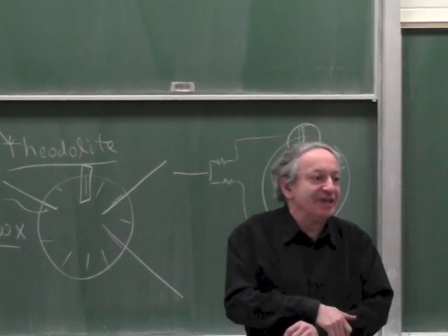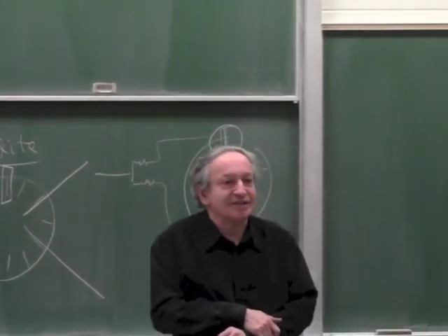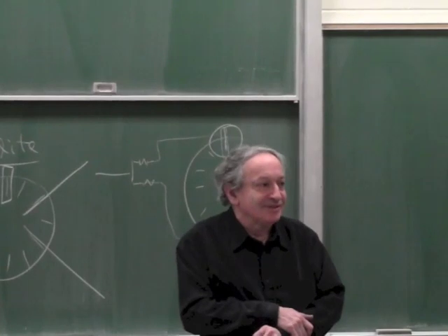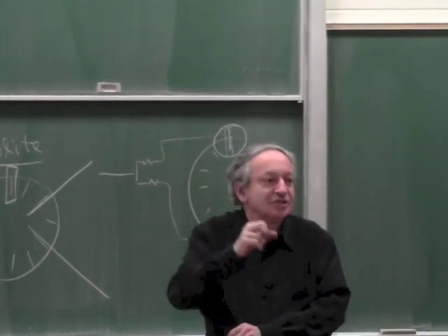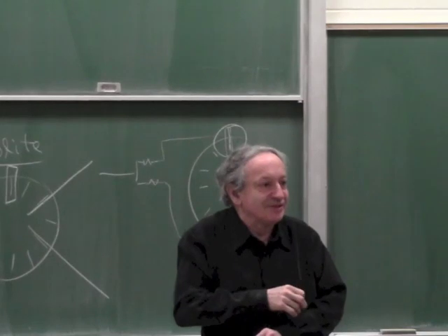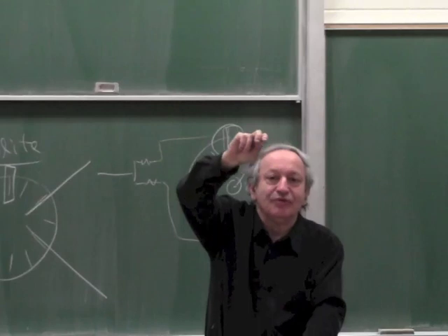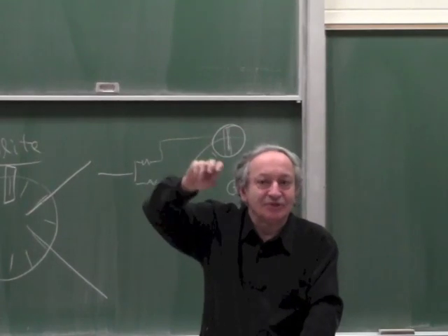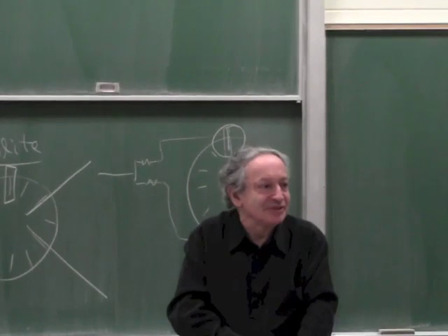So it's way too low a rate to do optical filtering because it's the same rate as the information. And unless you have a very slow moving target, by software you can filter it. Let's say you're following a crane and you know the crane can only move a meter a second, so what the software does is average many frames to get rid of noise.